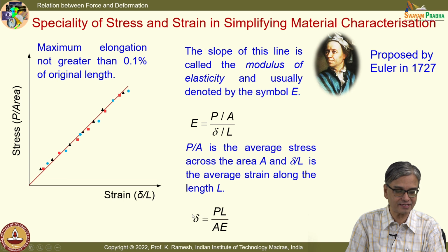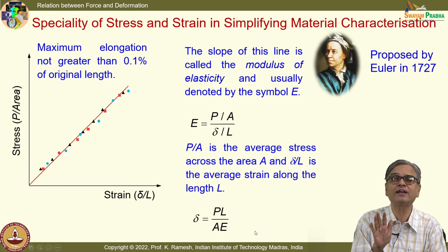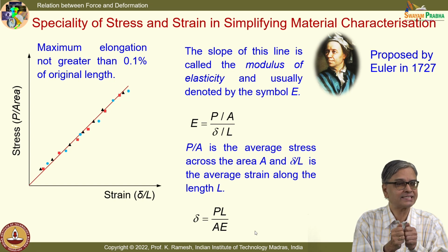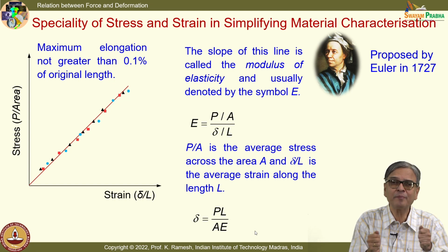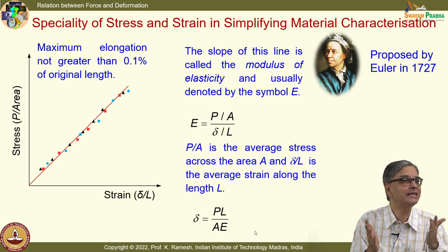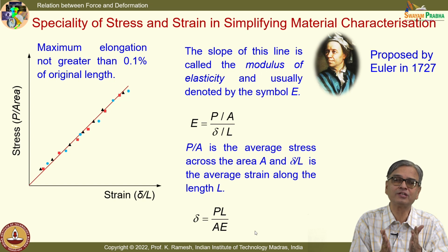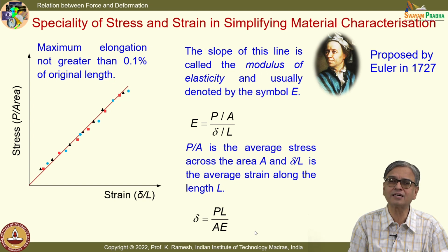And we will use this. I have this displacement as PL by AE, which is a very useful relationship. In an axial pull, the deformation, the change in length, is nothing but PL divided by A into E. We will use this to solve certain simple day-to-day problems.